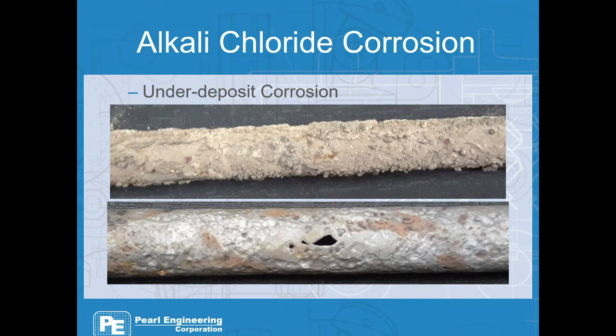and you can see the severe pitting on that tube sample that ended up coming out as a leak. That facility was forced to replace their entire secondary superheater assembly with an upgraded metallurgy, and we changed the controls slightly so that it would force the temperature range on that superheater down a little bit. There is like an 850 degree happy point for alkali chloride corrosion, so we tried to use the temperating sprays to help protect the tube life.